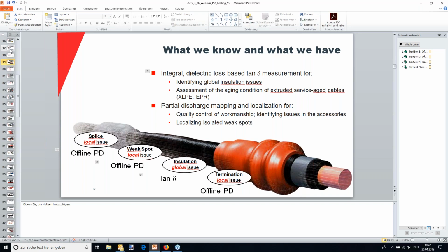Stay away from using dielectric, isolating materials to shield nearby objects. Let's say you are in a confined space switchgear and you disconnect the termination and bend it away to get some clearance. Do not put rubber mats over these other parts because that will make it worse. Why? Rule of thumb: if you have a sphere of 8 inches, 20 centimeters, around your disconnected termination, the influence of the other grounded objects is minimized and you should not get too much corona.